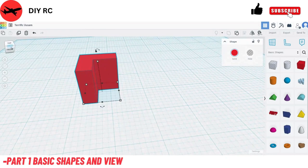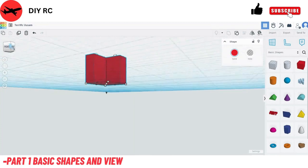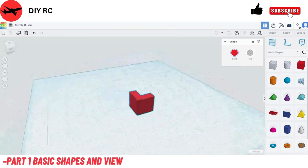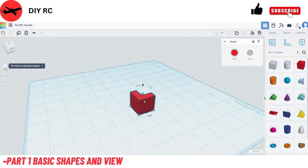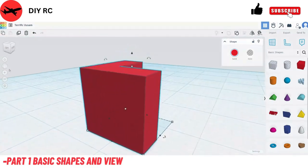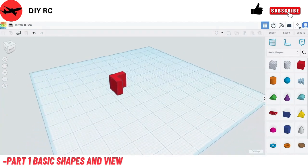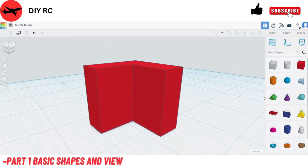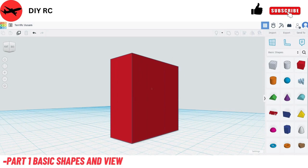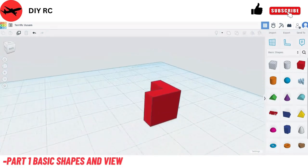Now, the way I'm moving around the view is our view cube right here. We can click on the faces to view our design from different angles. We can press the home button to center it, and we can press these parentheses to view the shape that we were working on. So you'll probably use this one the most, because if you get off, then you can just go back and right to center on the design that you were working on. You can tap on different faces, or you can right click and drag around to look around, and then you can scroll in and out with your scroll wheel.